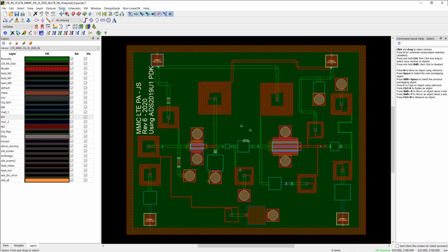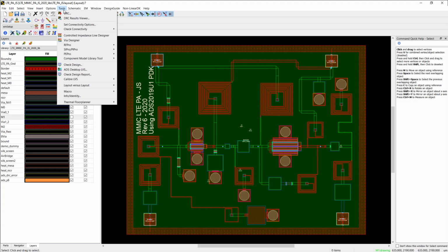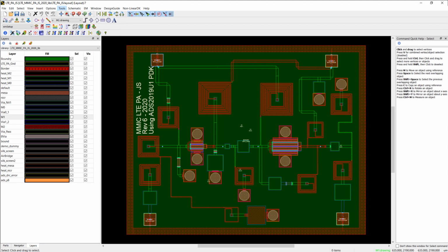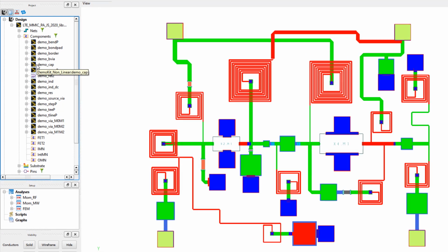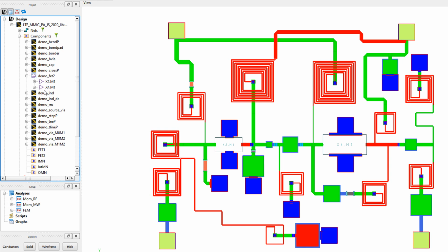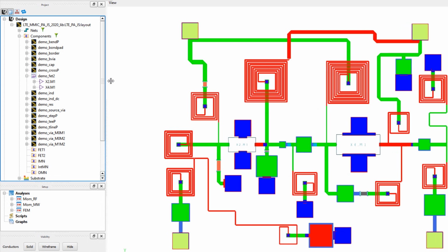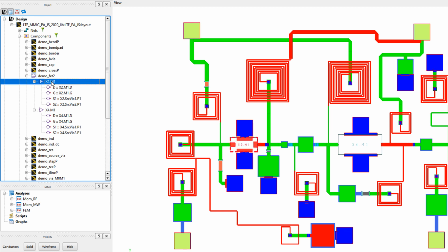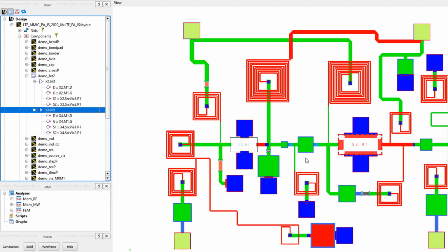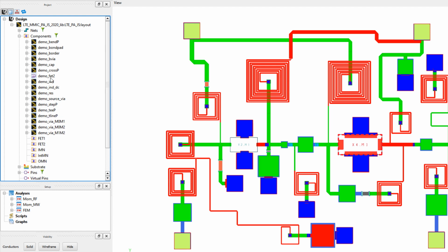Now here's a quick review on RF Pro. From the Layout page, RF Pro is launched from the Tools menu. Notice all components with the Layout view will be EM simulated. Components with the schematic view will be co-simulated with the EM. In other words, all circuit models or S-parameter models will automatically combine with the EM results, and this by itself eliminates any manual reconnection errors.